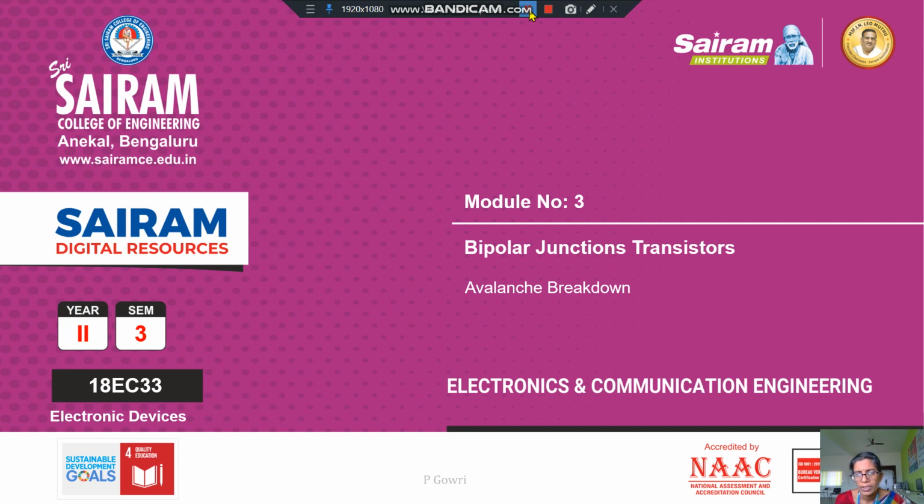In the previous videos we have seen two secondary effects. One is graded doping. In graded doping, because of the change in the concentration of the carriers, or we can say because of the change in the doping level in the base, an electric field is generated, which will result in the drift process. Because of that, there will be an increase in the collector current.